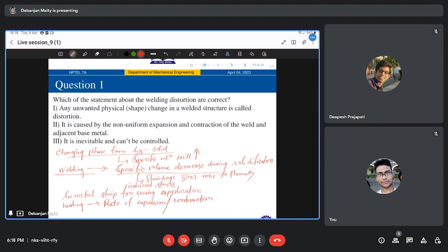So when you are doing something like this, let's say some hot dry glass cooking pot is suddenly placed into some cold water. So what will happen? The outside of the walls and the bottom of the glass pot cools faster than the inside, right? As a result of some thermal momentum, maybe, or because of some differentiation in the capacity of thermal dissipation, right? So some area will cool faster compared to the remaining portion. That also can induce your internal stress generation, right?